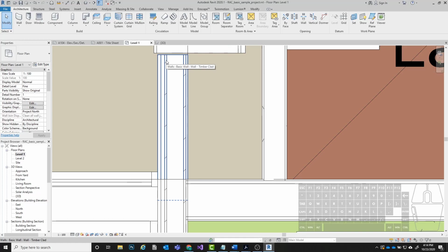You might have an underlayment or a sheathing layer if this is the exterior of a house. And then you might have your siding on top of that. If you're on the interior side of the wall, you're probably going to have maybe an insulation layer, and then maybe drywall, like a gypsum wallboard. So that's what all these little layers that you're seeing throughout the wall mean.